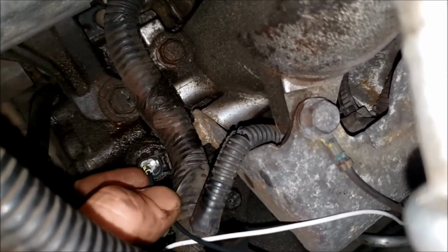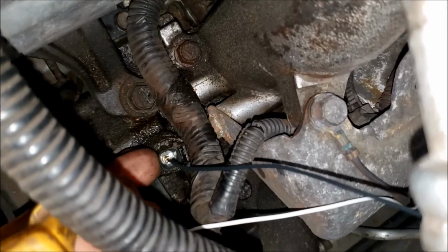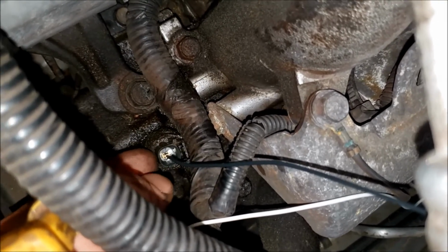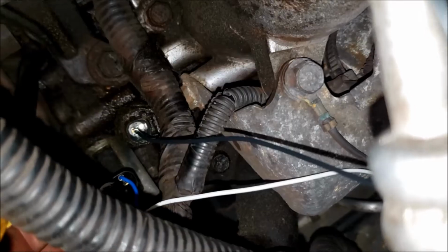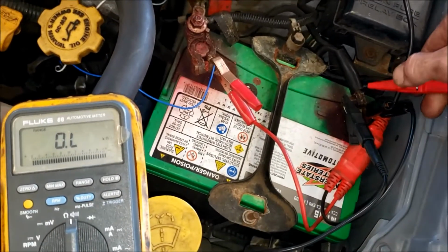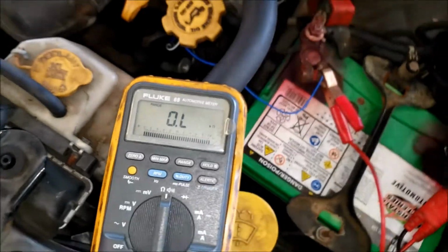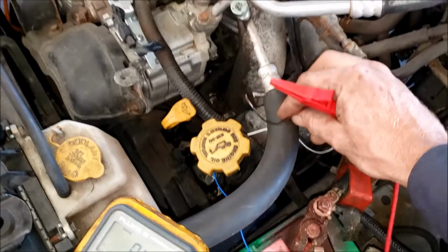All right, now we want to test our oil pressure switch. So I've got my wire pushed onto the terminal. This is a normally closed switch, and it should always be ground unless the solenoid is energized. So let's see what we got. I have black connected to ground. Let's hook this up here and verify that we're zeroed out. Okay, we are. Now let me hook it up to my black wire.